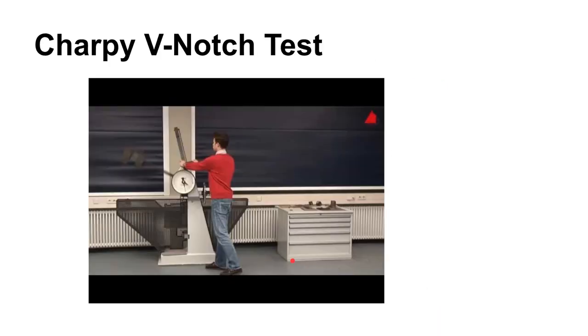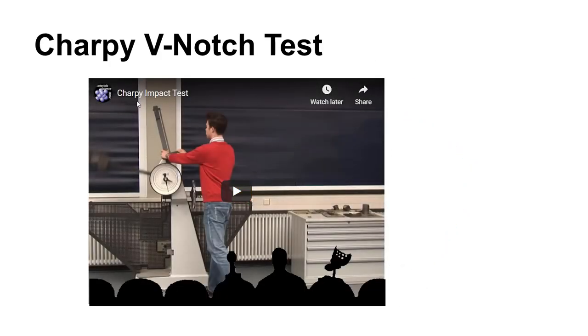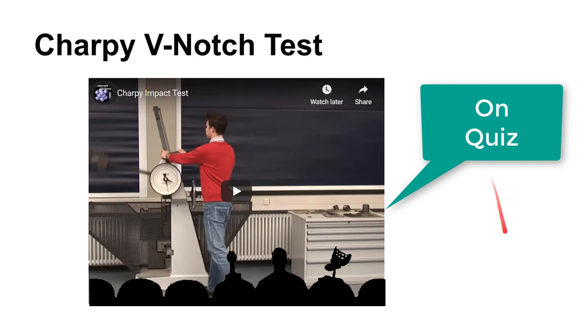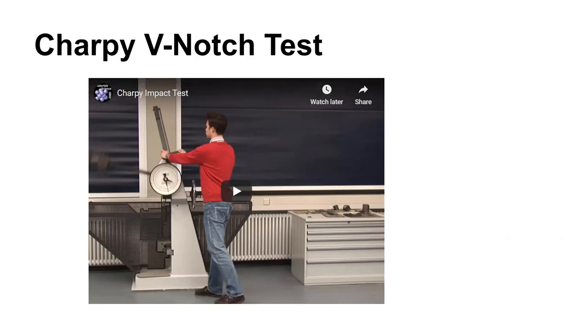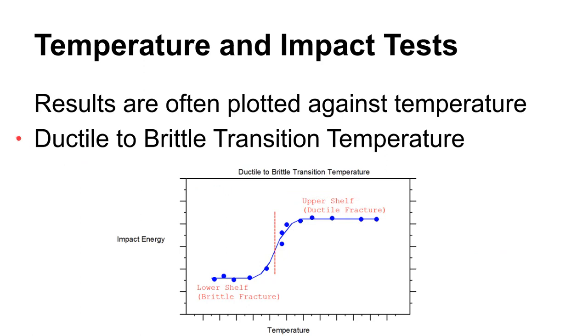properly. Here's again these folks doing a nice Charpy impact test. Okay, I mentioned earlier about the ductile to brittle transition temperature, and that is if we did a series of impact tests, and we started with a very, very cold specimen, and we did a test on that one, and then we allowed another specimen to heat up a little bit and did a test on that, and then let it heat up a little bit, and then did a series of tests across various temperatures.